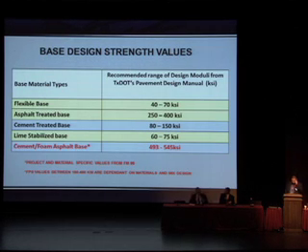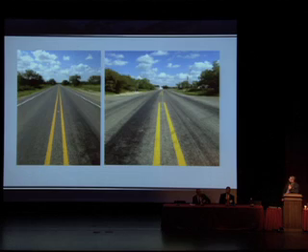So we didn't have a good handle as far as our moduli and what the foamed asphalt was going to give us. And what Tom and Joe Leidy and Mark have found is that our moduli came in very high. A 493 versus a 545. Now, of course, this is only one data point, so you really can't hang your hat on it. But depending on your materials, you could be looking at moduli in the 400 range. Okay, this is the picture of our finished product.